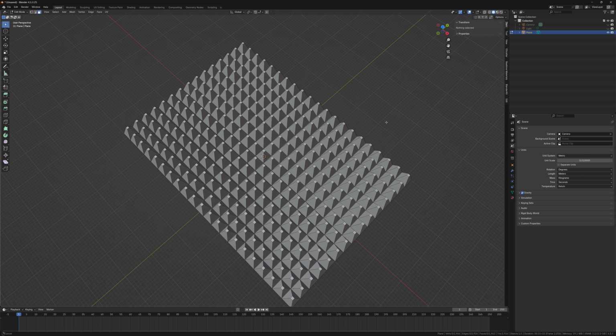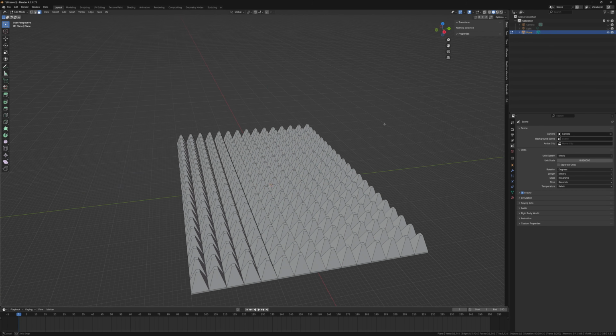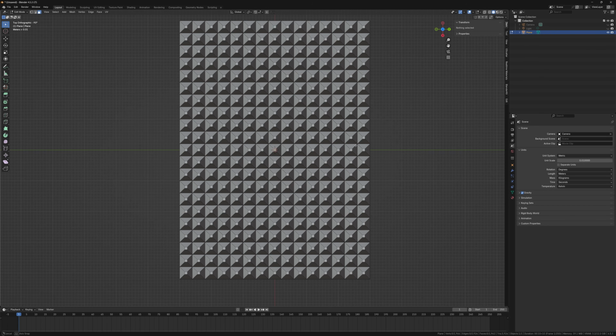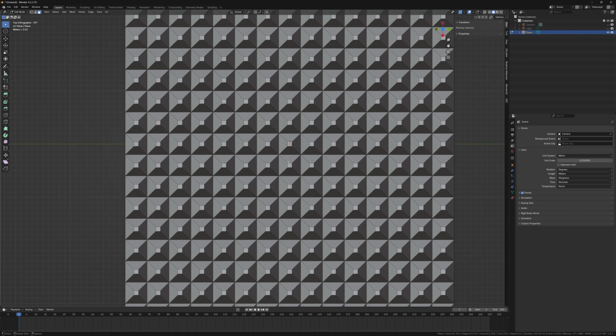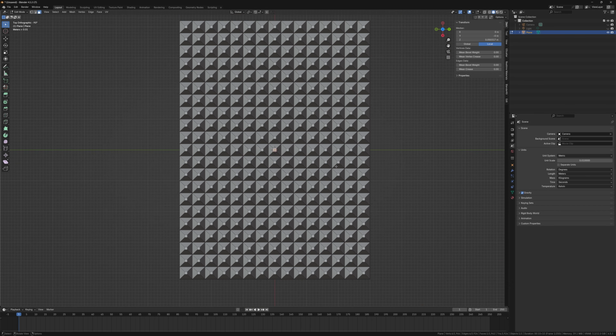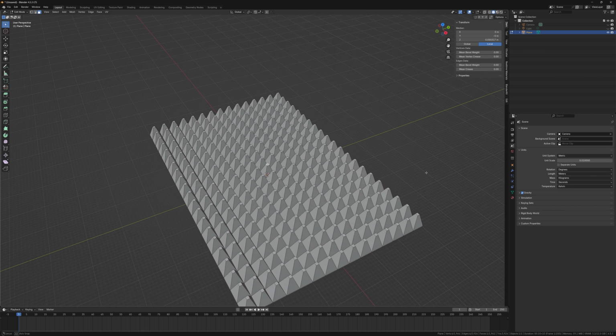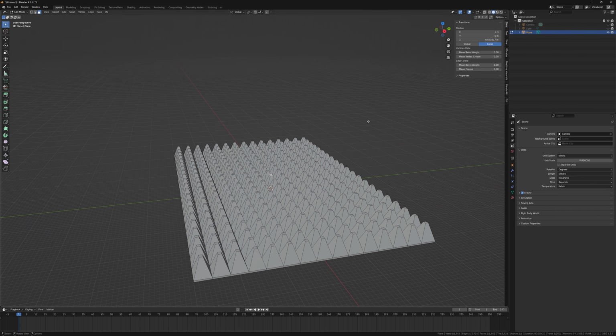But now for the even better part. We're going to look from the top. Again, snapping with Alt and then just dragging with the middle mouse. I'm selecting the center most grid piece. And then if we're going up here, there's proportional editing, or also shortcut key O. The key only works if you're not in any edit. So we can click it now. And if we do G and Z again, we can move this one.